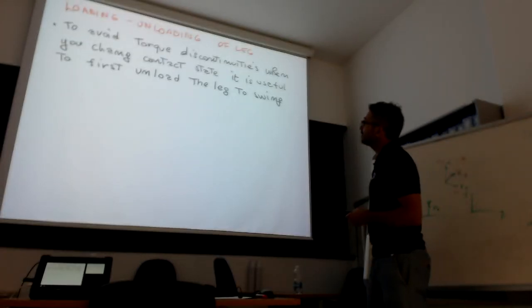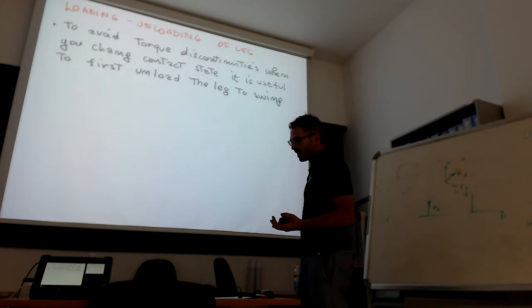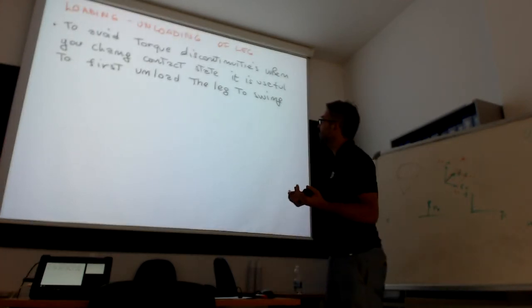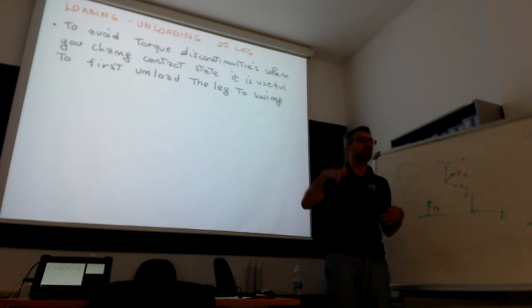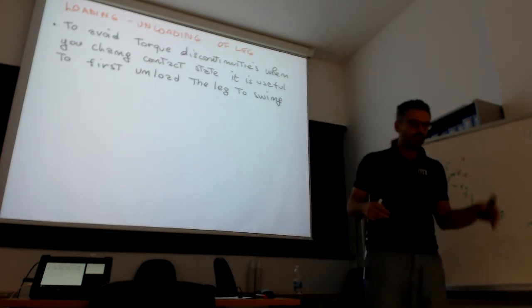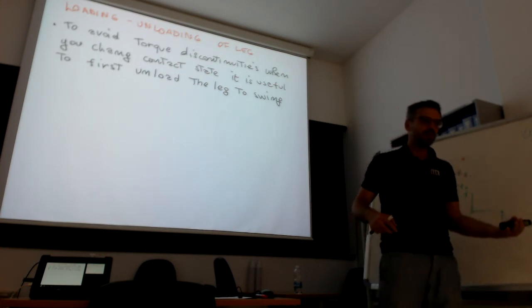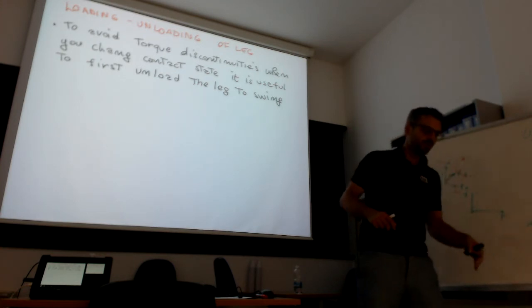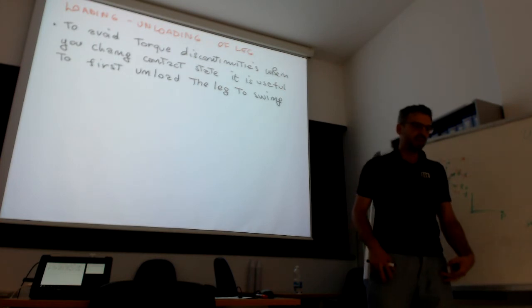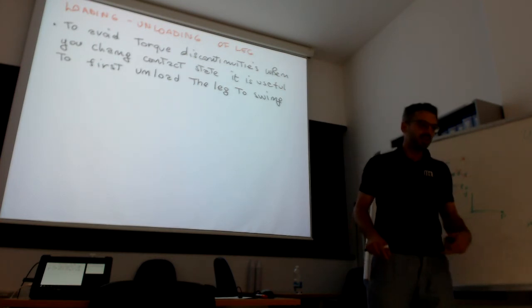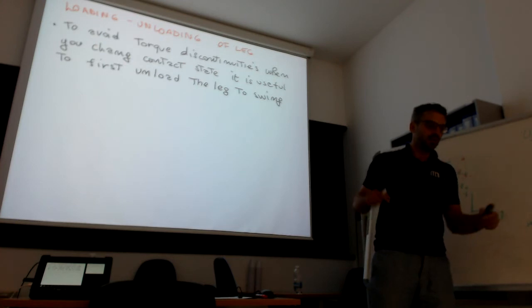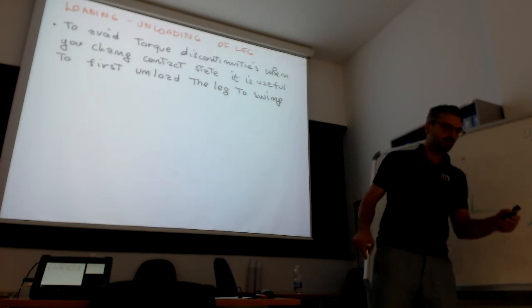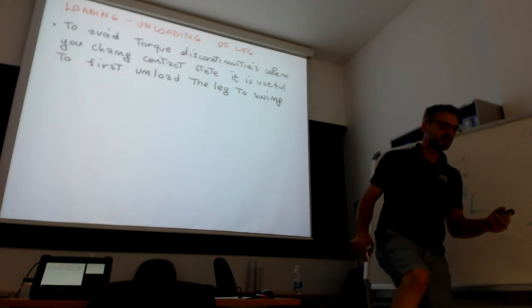So an important point, we talk about unilaterality constraints, so we want a positive force, but we might want also to control the loading of the leg. For example, if you want to move and start to swing, we want to first load the feet in stance that are not to swing and unload the force that is on this foot that I plan to swing. Whenever the force is 0, then I can remove it from the set of contact forces and start the swing.